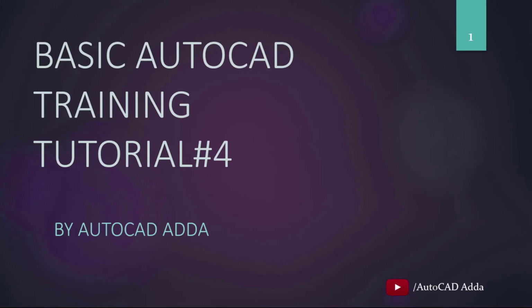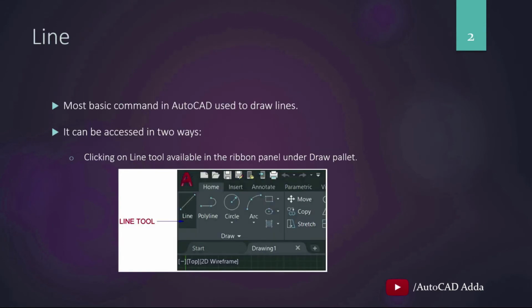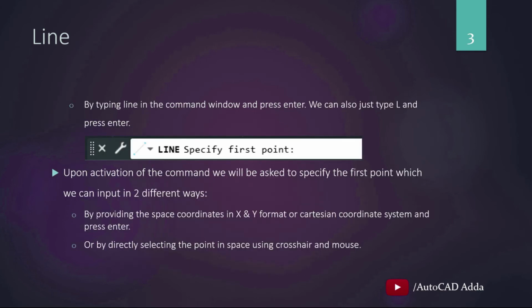Let us have a quick recap of whatever we have learned in this video. Firstly, we have seen the line command, which is the most basic command in AutoCAD, and it is used to draw lines. It can be accessed in two different ways. Firstly, we can click on the line tool available in the ribbon panel under the draw palette. And secondly, we can type line in the command window and press enter, or we can just simply type L and press enter. Once our command is activated, it will ask us to specify the first point as seen in the image on the screen.